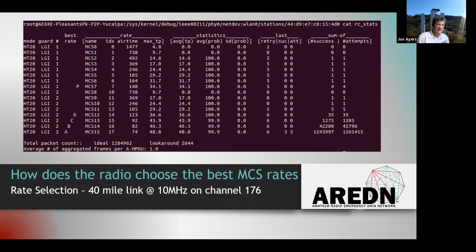On the receive side, all those receivers have to be able to detect what scheme is being used. So there's a lot of data encoding and pilot information that helps the receivers key on and figure out, oh, this transmission is MCS 15 or it's MCS 8, whatever. Every packet it receives has to go through that detection process. And every other packet I'm transmitting, if it went to another neighbor, could be at some different scheme and rate.